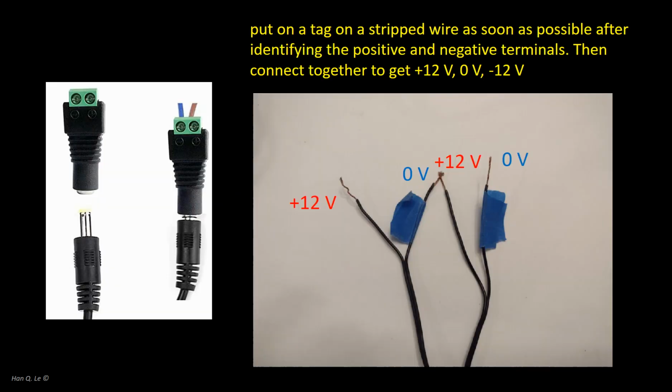If you don't have the type of connector adapter for a round jack to a pair of split bare wires, and have to do wire stripping of old AC-DC adapters, do a simple tagging on the wire as shown. Students had their op-amp burnt live on Zoom because they were confident of their memories of wire polarities, even though all the wires had the same color.